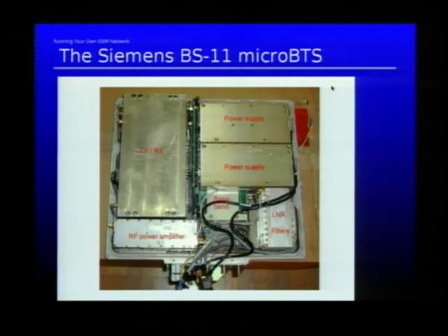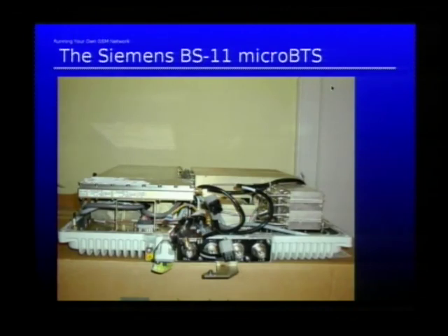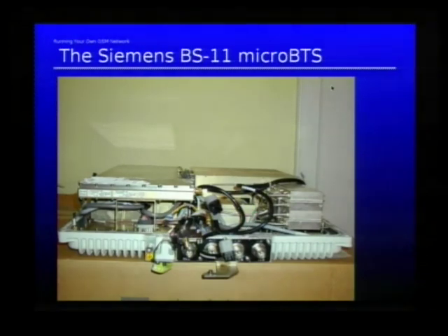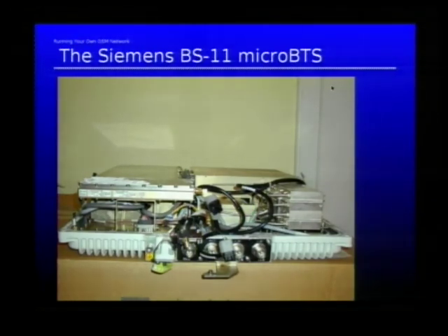We have several huge parts on the left, which are the transmitter and receiver. You only see this large block, but actually they are stacked. There are 4 boards stacked on top of each other, and they contain this information. You can see it on the next picture, that we have several levels. The layers are stacked, and the interesting thing is that this is really handmade work. There is a lot of metal inside. Metal is used in this case for thermal transmission of all the heat which is produced inside. This base station was manufactured about 10 years ago, and we don't have one single microcontroller which can do a lot of things. No, we have several. We have about 6 or 7 microcontrollers and 8 DSPs, and all of them produce a lot of heat. Therefore, there's lots of metal inside. Yeah, so actually this talk is about how to operate your own heating.